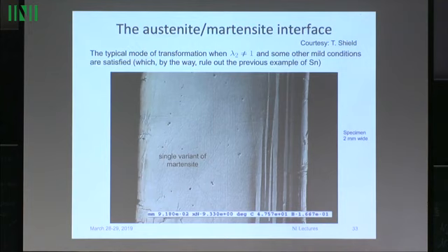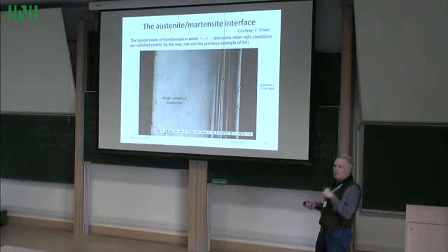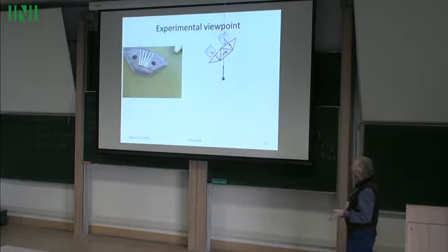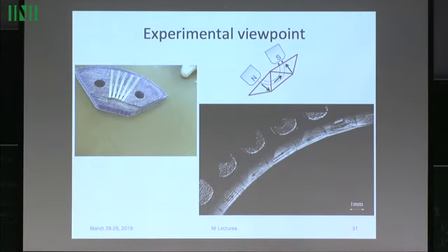The saturation magnetization in martensite and austenite in this material are almost the same, but the anisotropy is very different. If you're not familiar, anisotropy in magnetism measures the difficulty of rotating the magnetization vectors away from the preferred axis that was in any of these pictures, like I showed here. I try to rotate that.